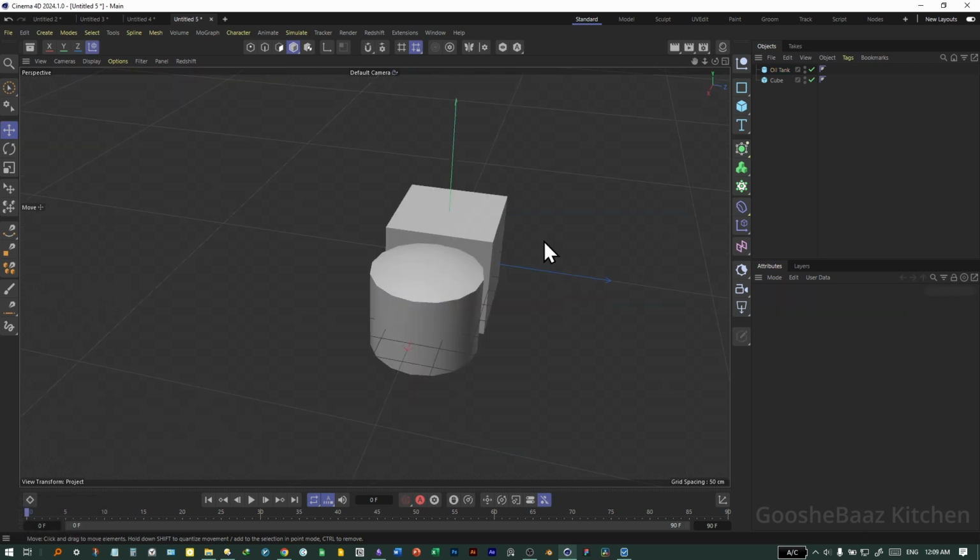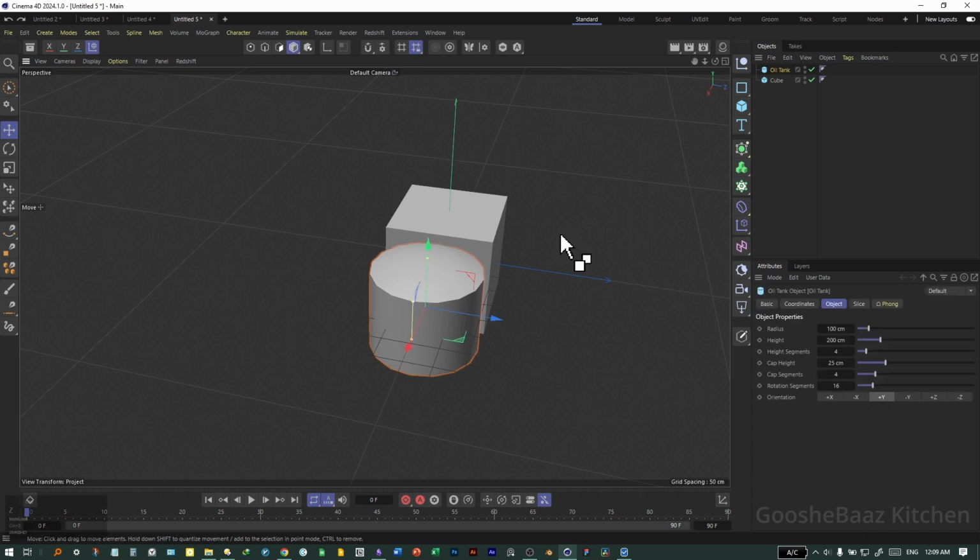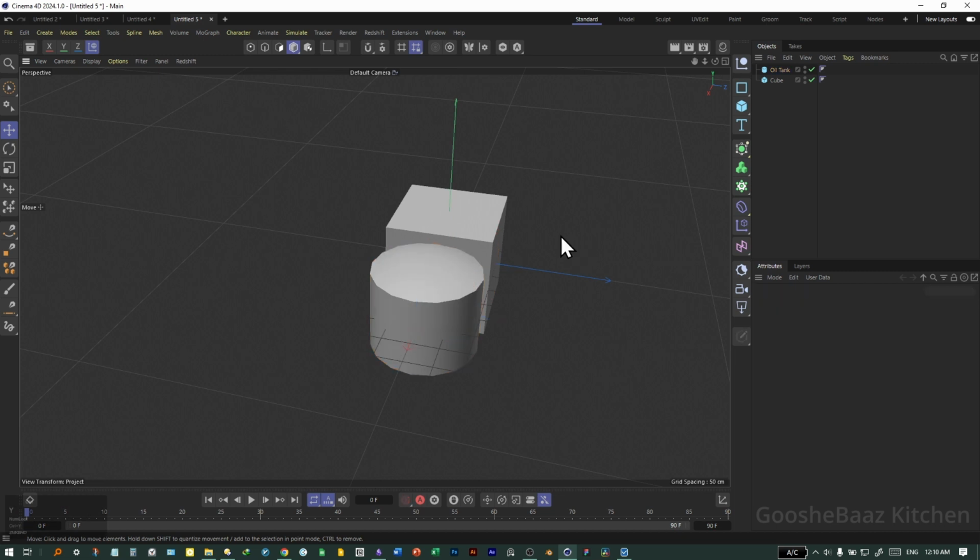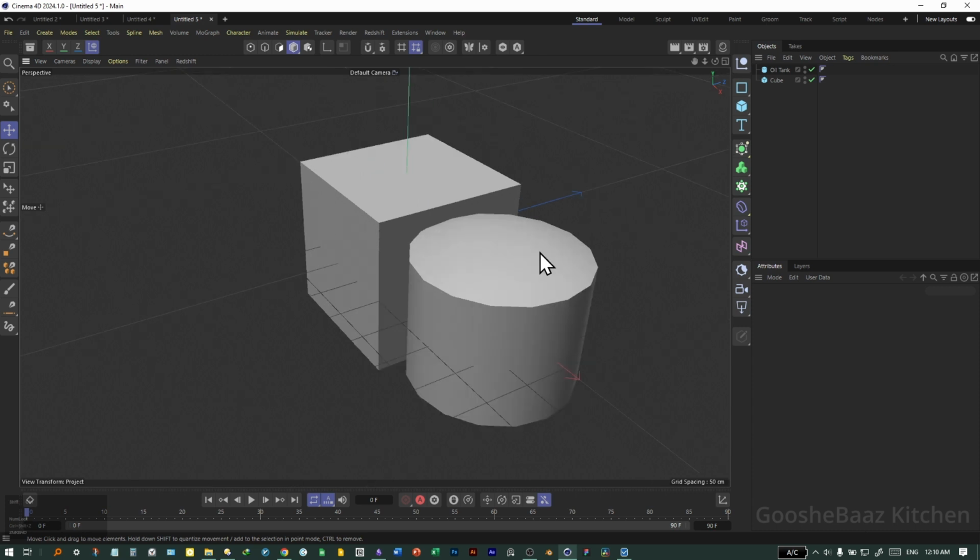In other software, Ctrl-Shift-Z is mostly assigned to redo, but in Cinema 4D, mostly like Microsoft Office apps, redo is for the scene, not the viewport. By scene, I mean operations like adding an object or doing other stuff: Ctrl-Z for undo, Ctrl-Y for redo. And for the viewport changes, Ctrl-Shift-Z and Ctrl-Shift-Y.